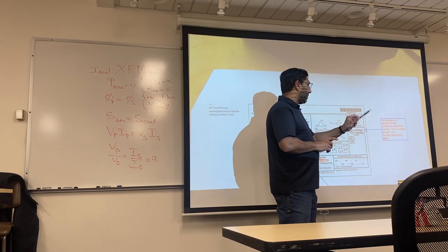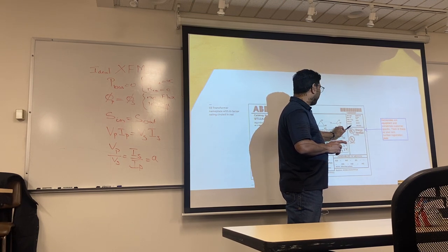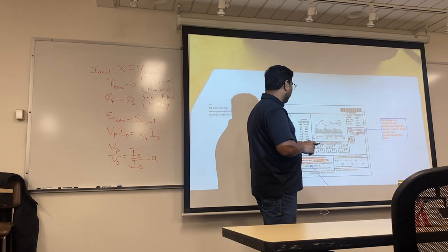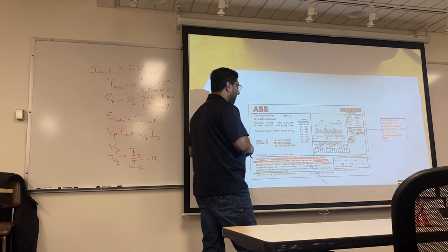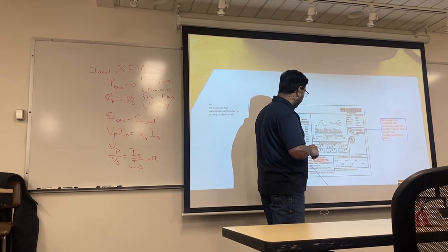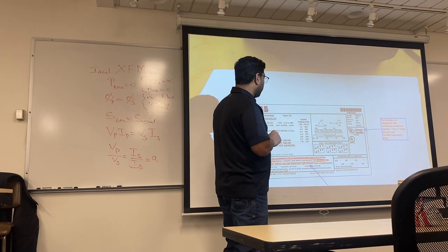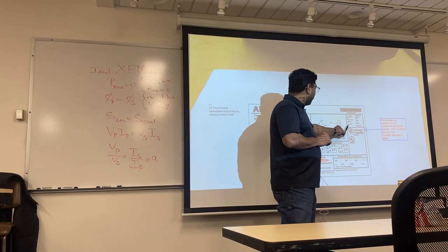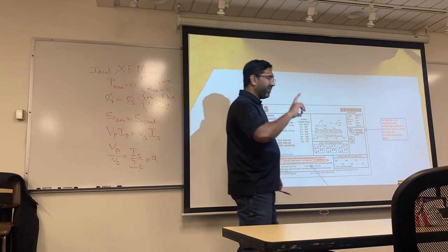Alright, so what does the other numbers mean? 75 amps. No. It's delta to Y 75A. So it simply means how you are able to connect these wires to get a certain connection. So remember the phase shift that I talked about? If you connect it this way, you probably are getting 0 phase shift, and you can increase it by 30 degrees.